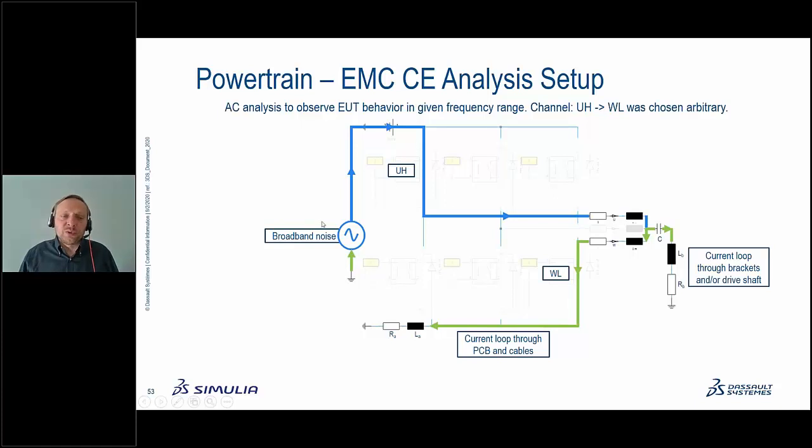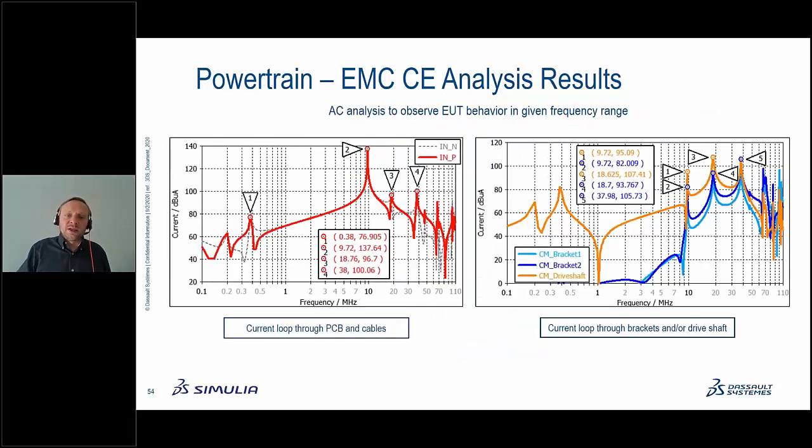And we look at this. Why do we do this? Because there's a frequency domain simulation, an AC simulation, inside the schematic, and it's simply faster than simulating these long switching times. So this is our first step. We will not stop here, but it's a first step which gives us the simulation results a little bit faster.